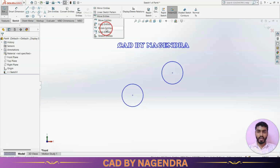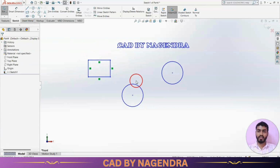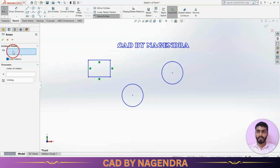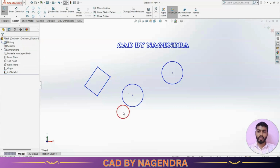Then next we are having rotate entities. Rotate is nothing but we are able to rotate this entire profile with reference to angle. Now let me go here with rotate entities. Entities to rotate is this. Then center of rotation: with reference to which point we need to rotate this. Let me select center point is this. Then with reference to that, how much inclination we give, that much it will rotate with reference to this particular selected center point like this.